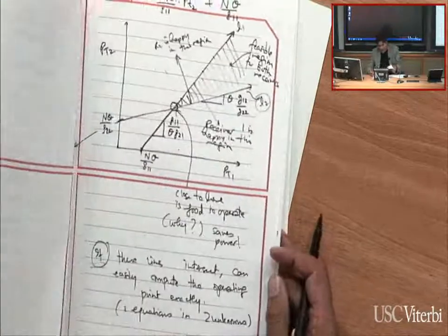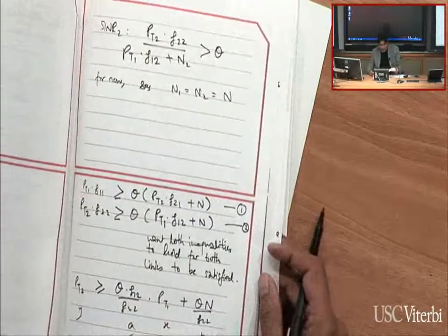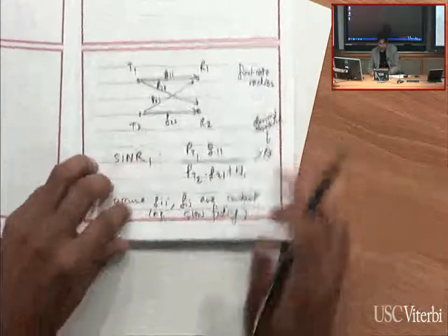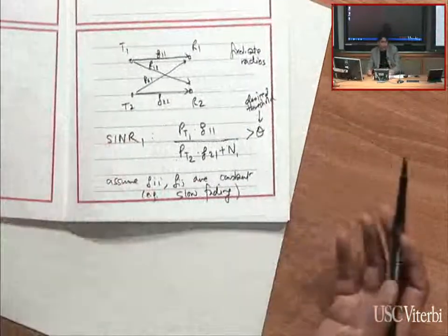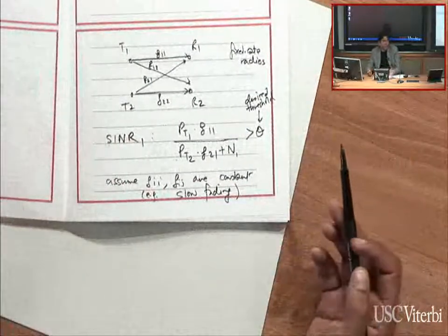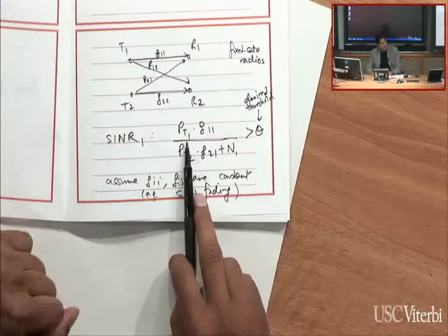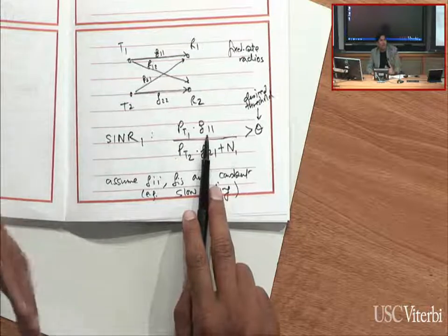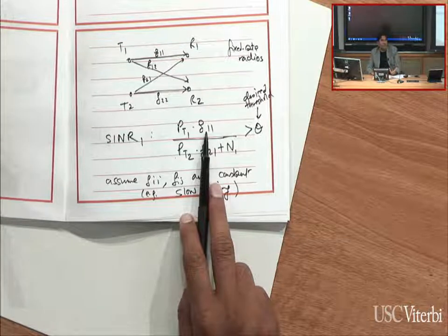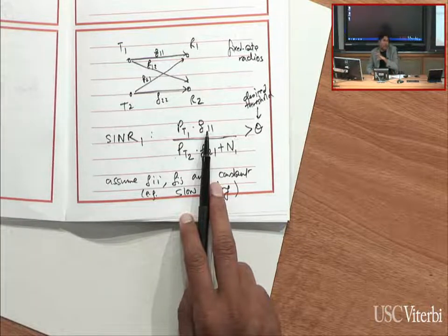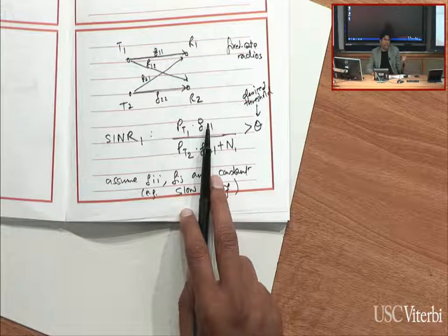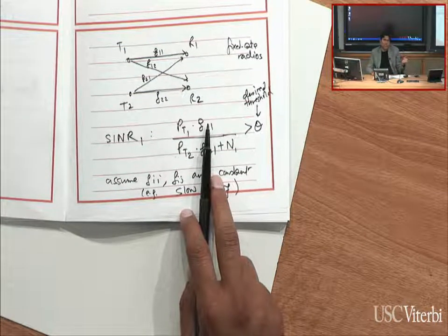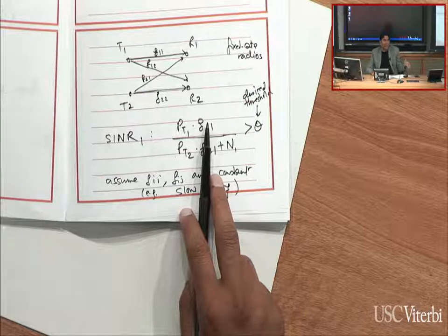So in fact, these equations for SINR that we're describing hold identically for acoustic communication. This power level could be how loud you're talking. This gain is the inverse of how far away you are from the person you're talking to. It turns out that acoustic waves also decay with distance roughly as 1 over distance squared, for the same reasons that the radio signals decay.